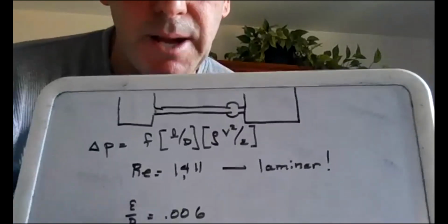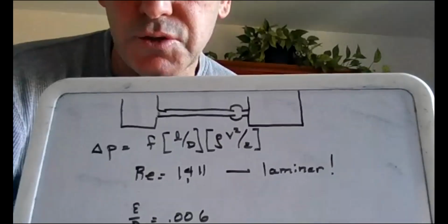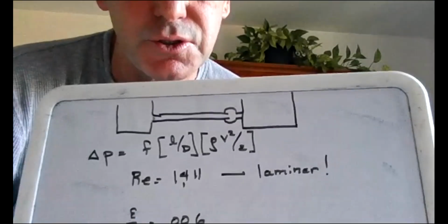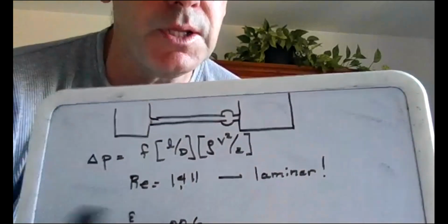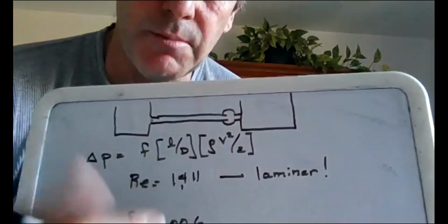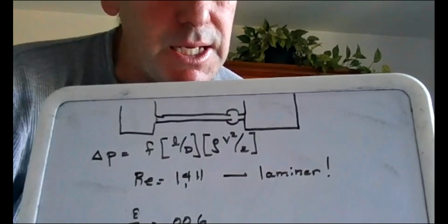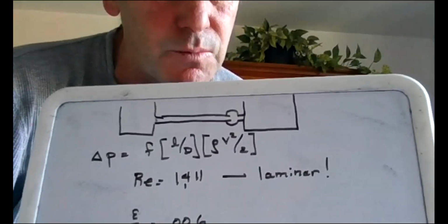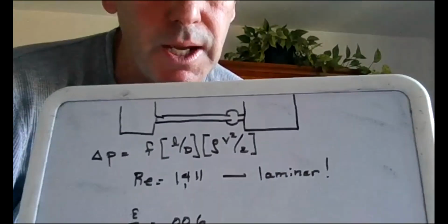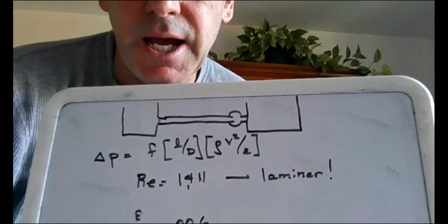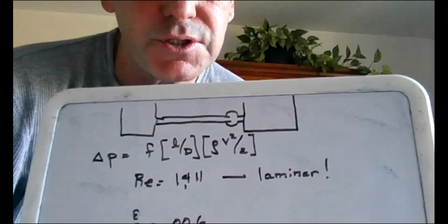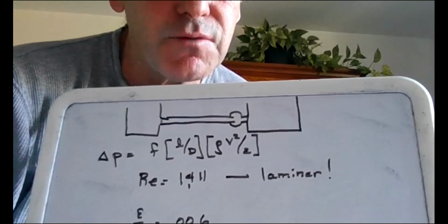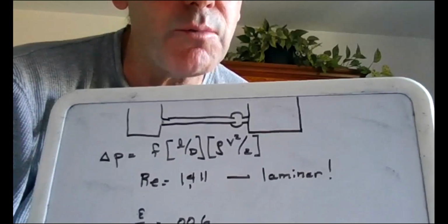So we talked about going over to this roughness and getting that value. So we're on this 0.006 curve. That's one thing we need to do. Second thing, following my instructions earlier, is we need to get the Reynolds number, vertical line. There's 2,000, we're laminar. We're somewhere in here like this. The thing to understand is, if I follow this 0.006 line over, horizontal, curving up, curving up, curving up, it doesn't make it all the way back.